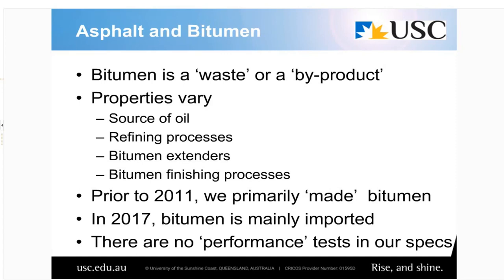I've never been convinced that spraying some bitumen on the surface of the flank necessarily creates an environmental concern, but I certainly acknowledge that there have been examples where seal has been used only because of the perceived environmental concern of spraying bitumen on top of the flank material. So that's a good point and well worth being conscious of. Although I'm not an environmental person, so I couldn't necessarily comment on the validity of the concern, it's never really rung alarm bells to me.